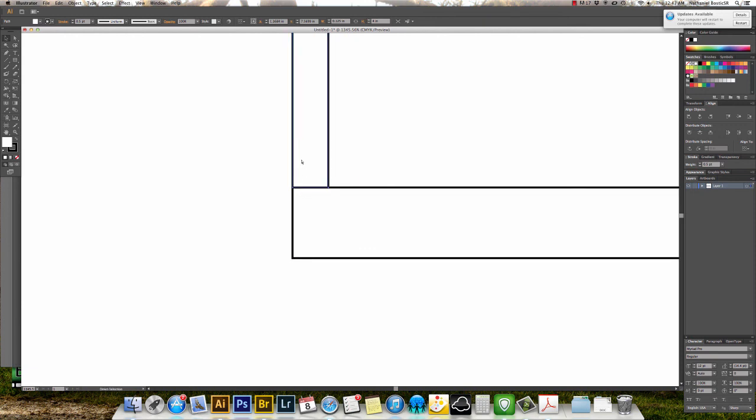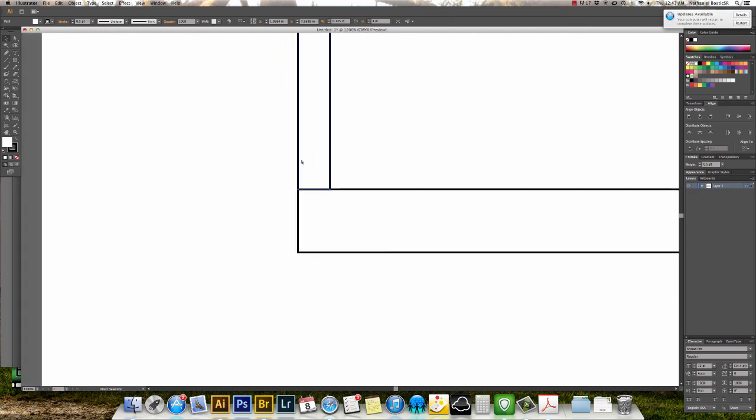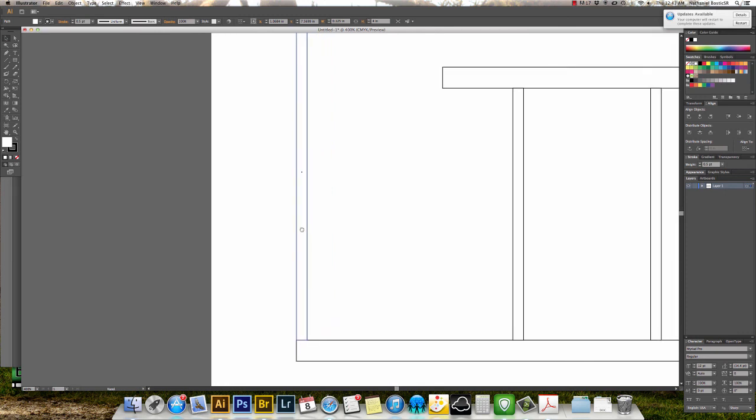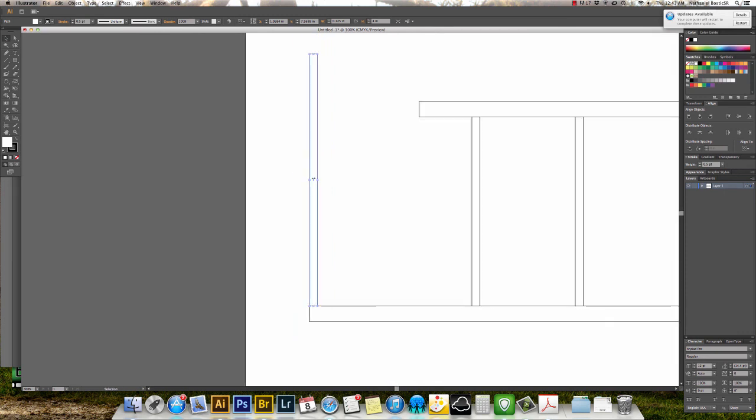Now comes the part that you gotta pay attention to. I am now, zoom out a little bit more. I'm now going to rotate this. So if I go to my rotate tool in my toolbar, alright, or press letter R, I click it and you notice I get this little light blue thing here in the middle, and it says center. That is called my origin. If I was to rotate this right now, notice it moves around that origin. Alright, but I don't need it to move like that.